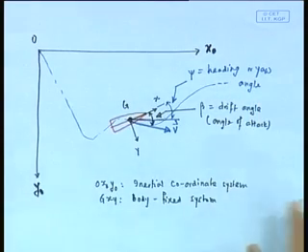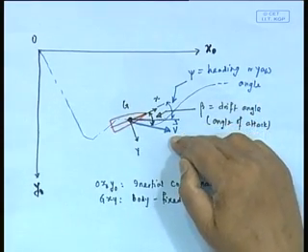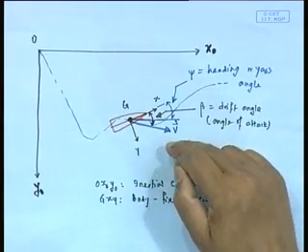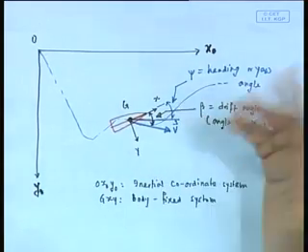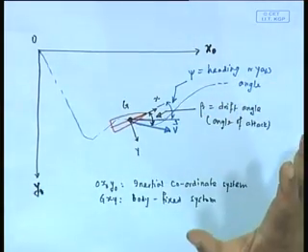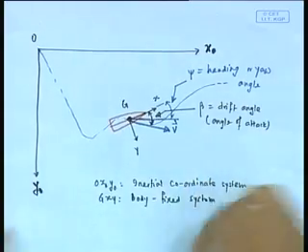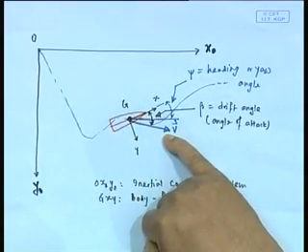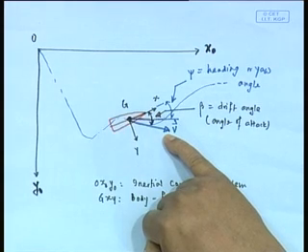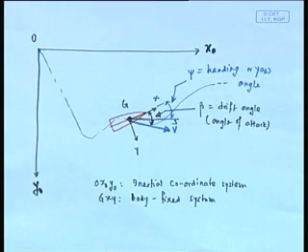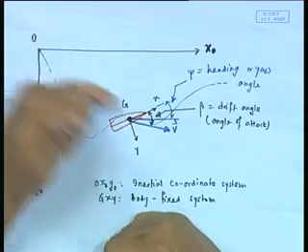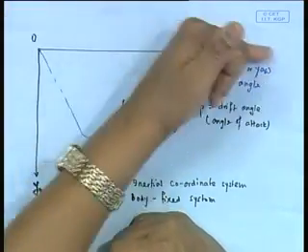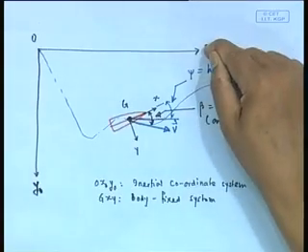See here, drift angle is the angle between the velocity vector and the x axis. That makes sense. Okay, let us take it slowly. The drift angle is the angle between the velocity vector and the x axis, whereas the heading angle or yaw angle is the angle that it is making from its original heading. That is the heading it makes with respect to the x0 axis.